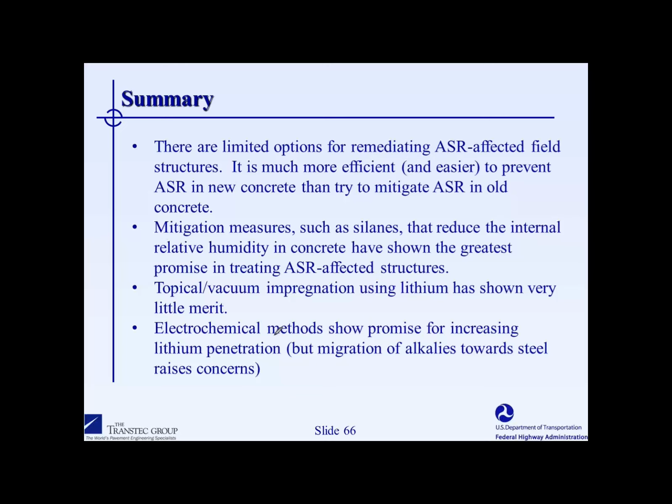And Matt, if I can just add one more point to Benoit's. First of all, thank you, Benoit, for that response. We've done some work with the Texas Highway Department where we developed a recommended practice for the application of silane, and that very question came up again: how often should you reapply? Our recommendation was, I guess, a bit of taking the high road, but we said one should monitor the internal relative humidity, and if that relative humidity begins to rise with time, then we can consider that the silane's efficacy is beginning to wear off, and you should consider another treatment. So that would be one way to determine whether you need to reapply it: measuring the relative humidity of that section compared to a control.